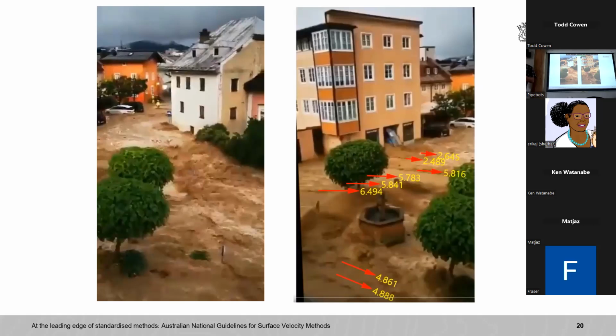Are you building stage discharge relationships with the information that we're getting? Yes, for the high flows. And again with the fixed cameras, I've got 4 more to go in this year in remote sites up at York. They'll be left up there 6 months over the wet season, and then we will process the videos, which is a couple hundred.